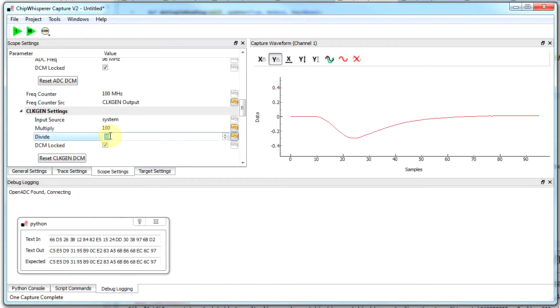So we're going to start to see them differ as the system's failing, as it approaches its maximum speed. So let's not go quite to 120 megahertz. 125. So somewhere around 120, 115. We can see here the text out and the expected is occasionally differing. So the system timed out here. Let me just redo that. So we're starting to see failures, and we're seeing timeouts here as well. So that seems to be almost the upper limit, which is below the expected 125 megahertz.